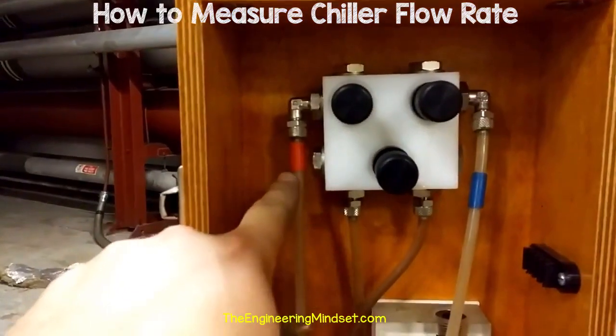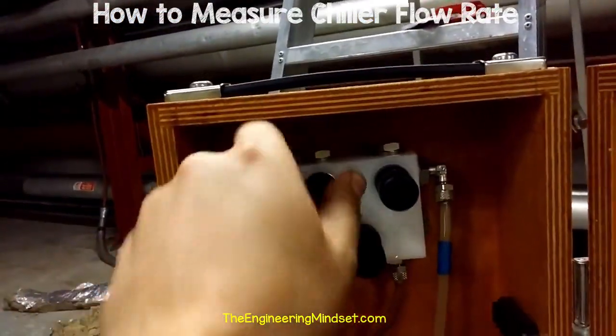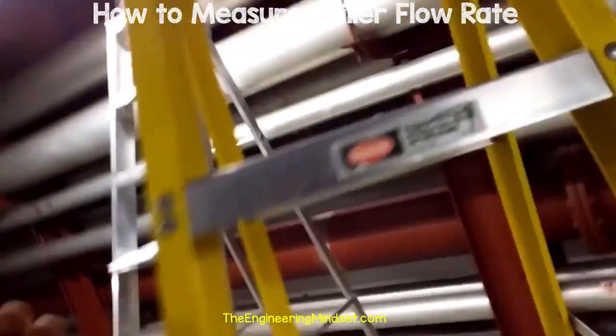Then open up the manometer and find your high pressure side, which is coloured red. Ensure that the 2 top valves to your high and low pressure side are both fully closed, and that the lower middle bypass valve is fully open. Then connect the red high pressure hose to the high pressure tube of the orifice plate.